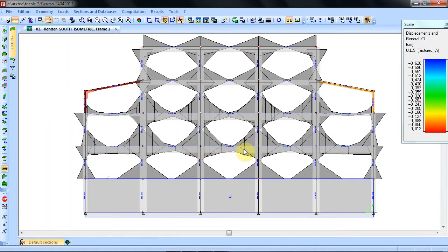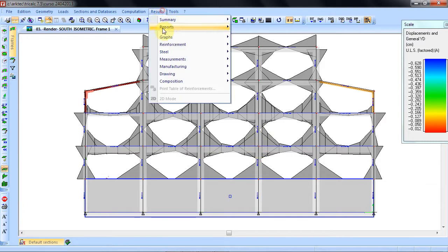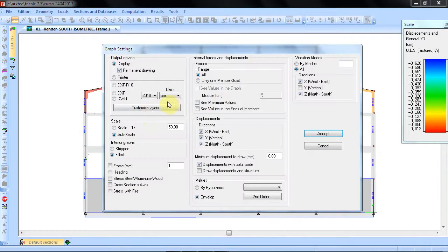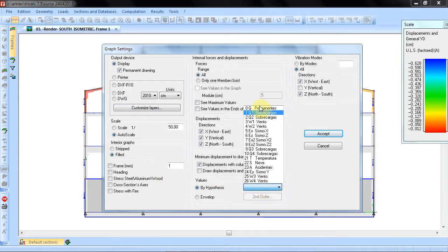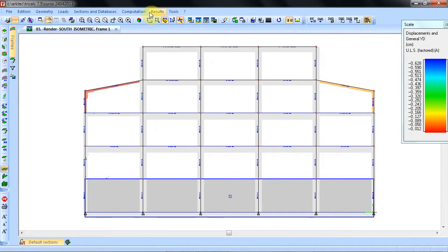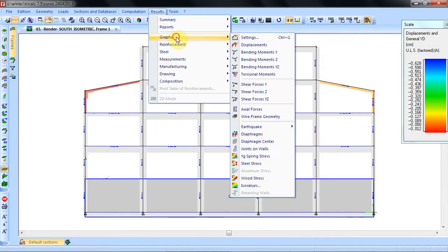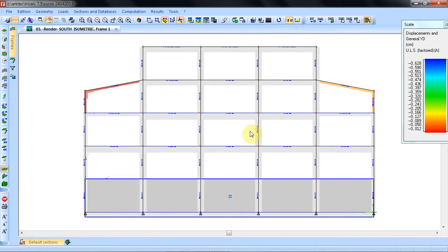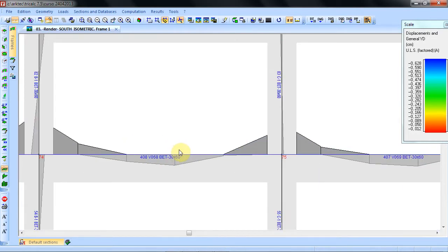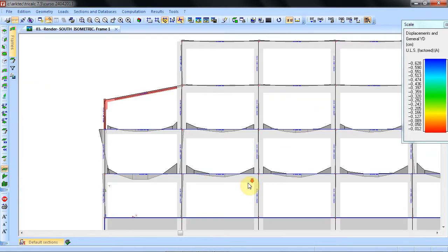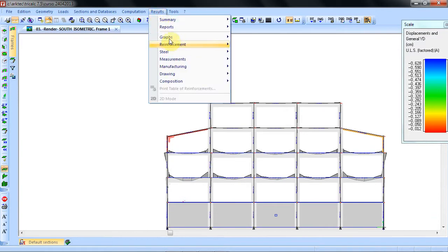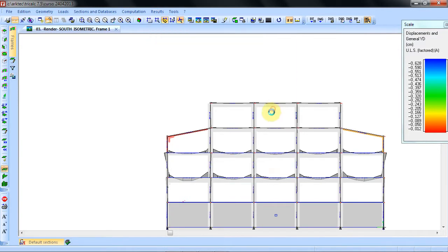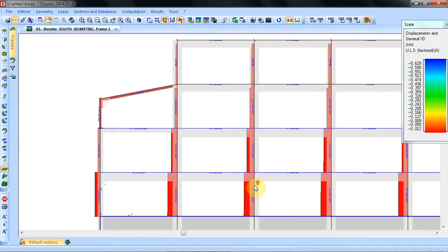This is a representation for the envelope graphic, but we can define, for example, for the dead loads, the representation of the bending moments. This representation can have the values displayed in the graphic. We can also check how the program shows us the axial forces on this plane.